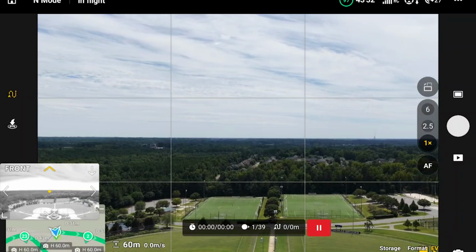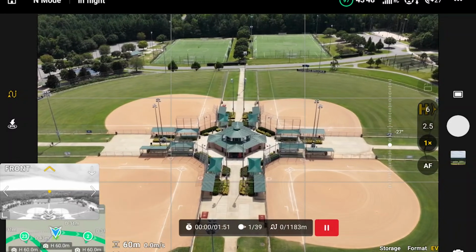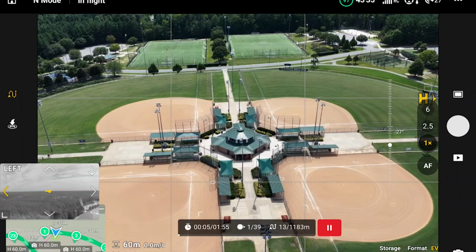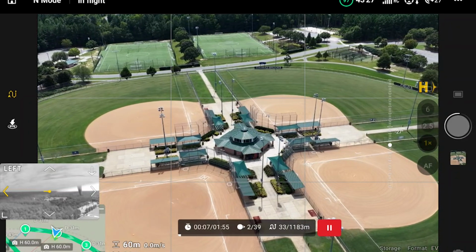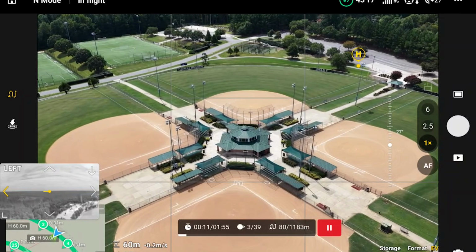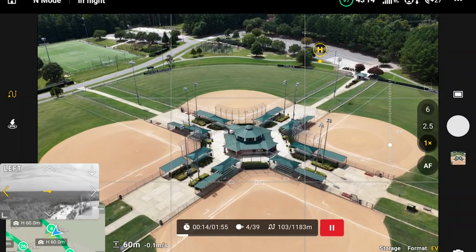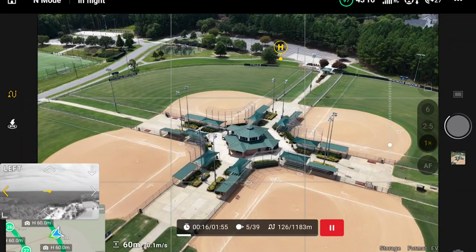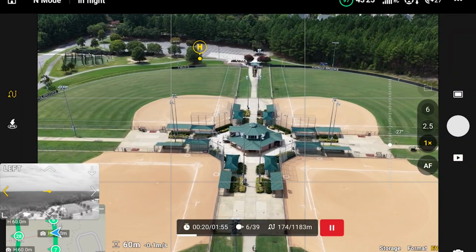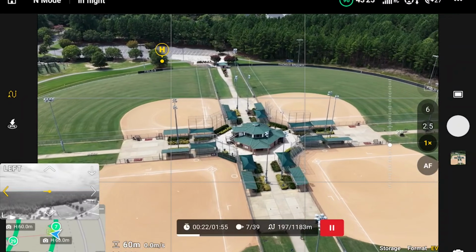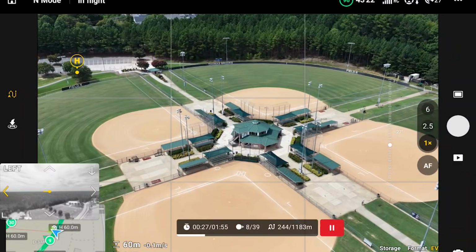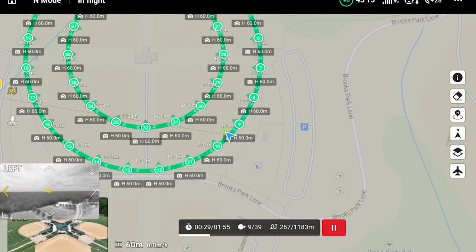If you are on the free version, before you get started here, you'll need to enable the time shots feature. That means that if you did not generate waypoints with action and you're using the free version, which is perfectly okay, you just need to make sure that you set your camera mode to time shots and turn that on. So instead of it taking pictures at each waypoint, you're just taking pictures every X amount of seconds, whether that be 1, 2, 5, etc. That way, as the drone flies around, it will still follow the same path. It will still do exactly the same thing, and you'll get pretty much the exact same result.